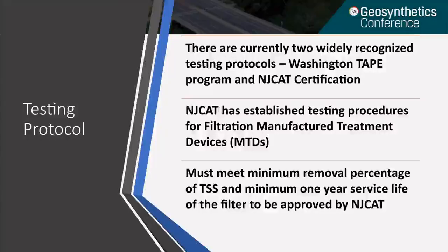There are some established testing protocols. There are currently 2 widely recognized testing protocol programs: the Washington TAPE program from Washington State and the NJCAT certification program out of New Jersey. NJCAT has established testing procedures for filtration manufactured treatment devices, or MTDs. These standards must meet a minimum removal percentage of TSS and a minimum of a 1-year service life or greater of the filter to be certified by NJCAT.